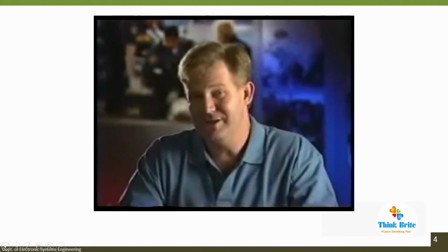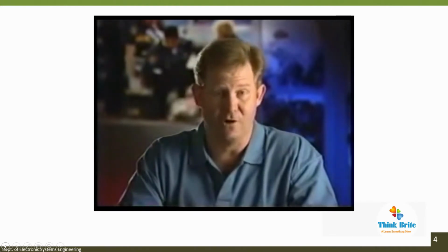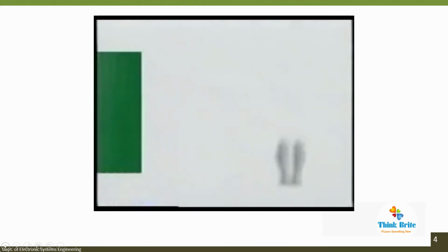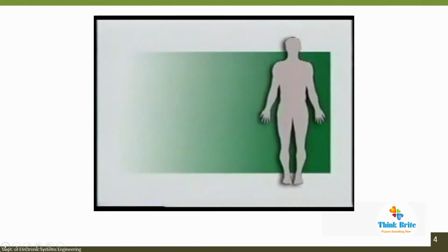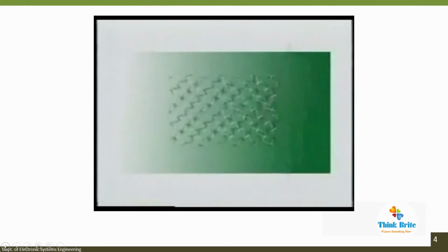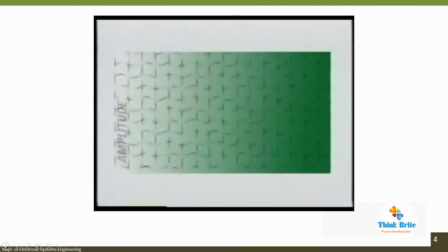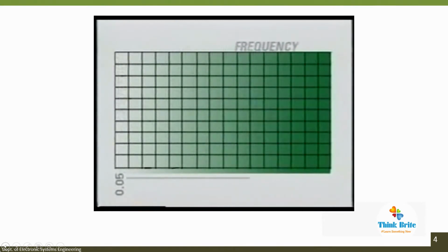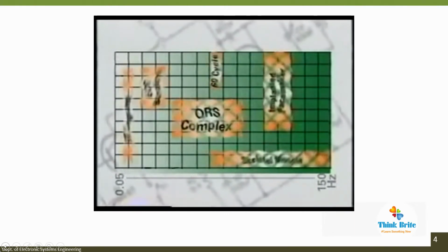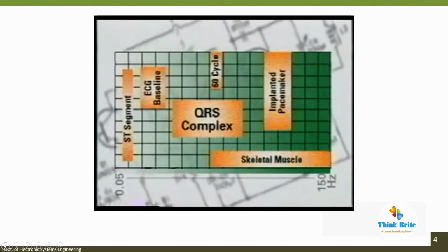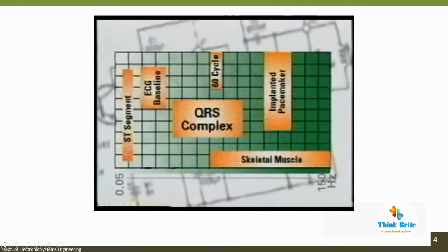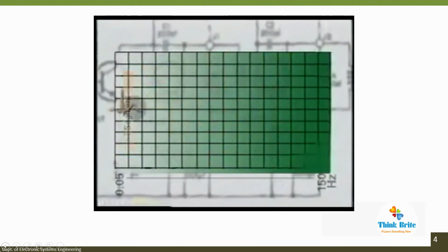To get a 12-lead ECG, we must isolate only the heart's electrical signal. The human body and external environment have many sources of electrical signals. The electrocardiograph can detect and reproduce the various electrical signals of cardiac conduction. The monitoring frequency response mode provides a 0.5 to 40 Hz view of cardiac conduction, while the diagnostic frequency response mode provides a 0.05 to 150 Hz window. This broader frequency bandwidth accurately reproduces cardiac electrical data necessary for diagnostic interpretation of the status of the myocardial muscle, which may be reflected in the ST segment of the cardiac ECG complex. The ST segment is found in the lower end of this electrical frequency window.